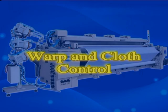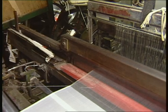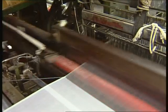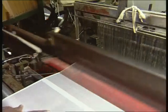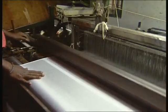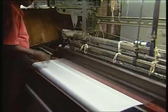Warp and cloth control. After beating up the weft into the fell of the cloth, a take-up motion draws the cloth forward and winds it onto a cloth roller. At the same time, the warp is delivered from the weaver's beam by a let-off motion.